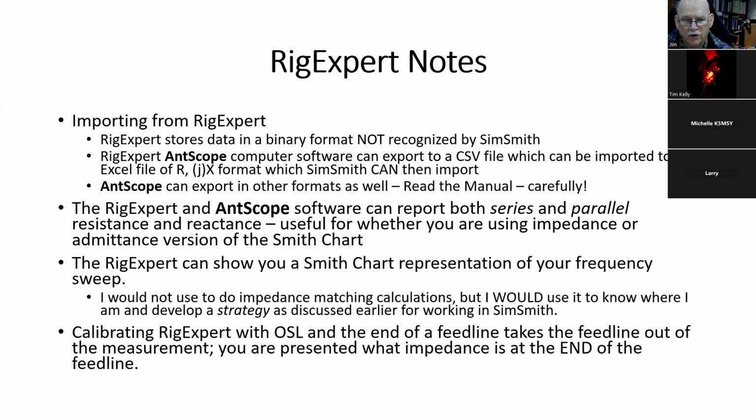And the third bullet there is kind of important. Antscope can export in other formats as well. Read the manual carefully, and that manual is less than 20 pages. And what I really like is the Rig Expert and Antscope software can give you both or either series and parallel resistance and reactance. That is a useful capability because it means you don't need to do a conversion.